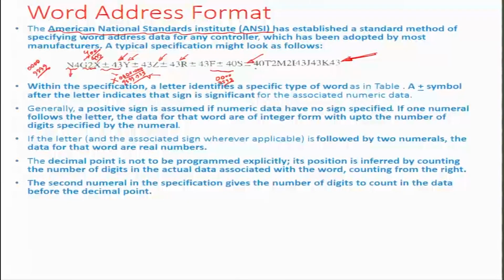You have the option of, so this is a certain controller that they are defining capability wise. Option of speed again, the tool option, which can define about 100 tools. Again, the controller way of understanding miscellaneous options from the standpoint of 100 different miscellaneous operations, M00 to M99, and then these individual circular interpolation parameters, which are again linked up in a similar manner.